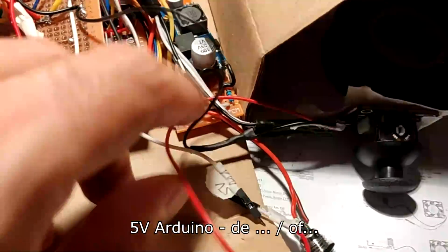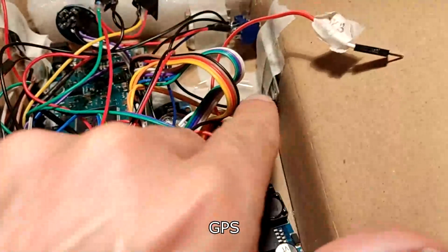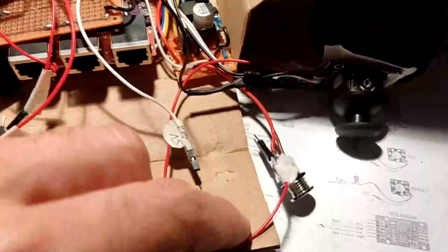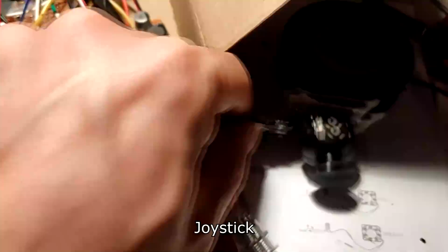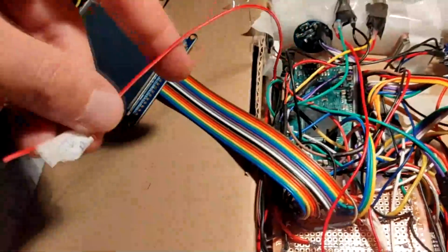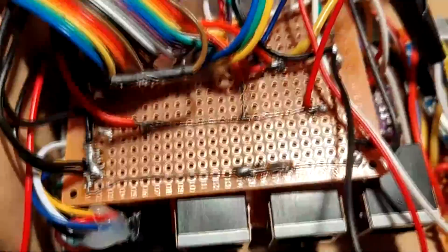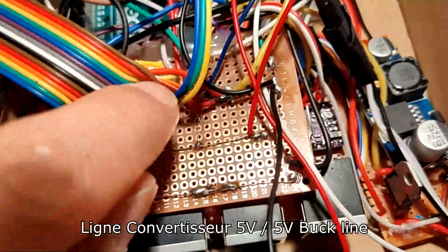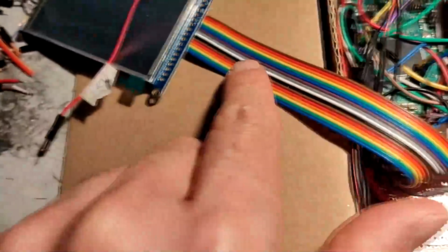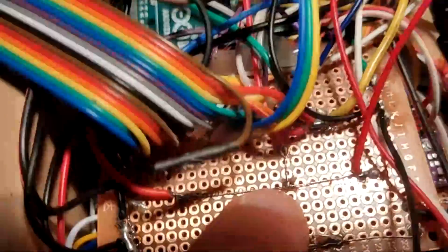I'm gonna do the same for the 5 volts Arduino, so the GPS module. This is the wire for the joystick. These two wires will be connected to this wire, which is the 5 volts Arduino output. The wire to connect the screen was a little short, so I made a second path coming from the main path of 5 volts buck.